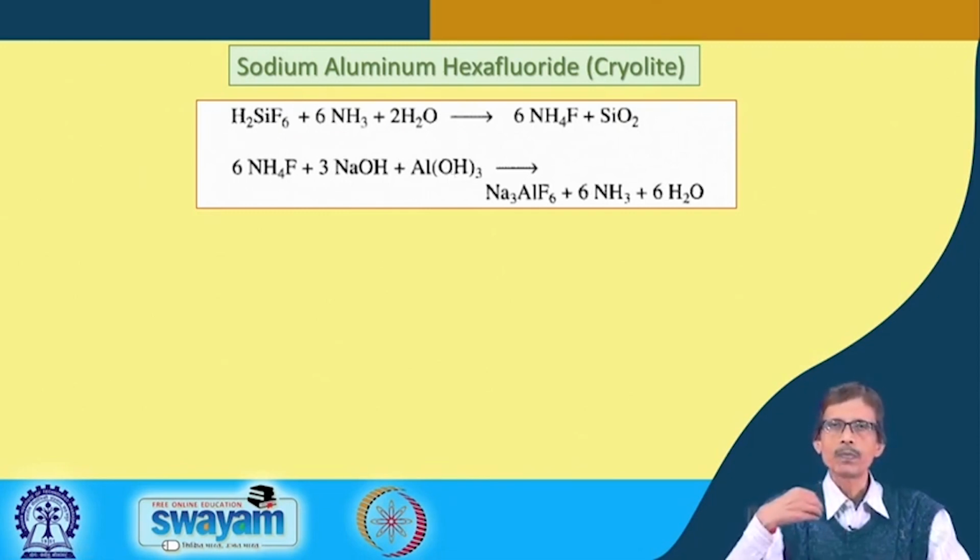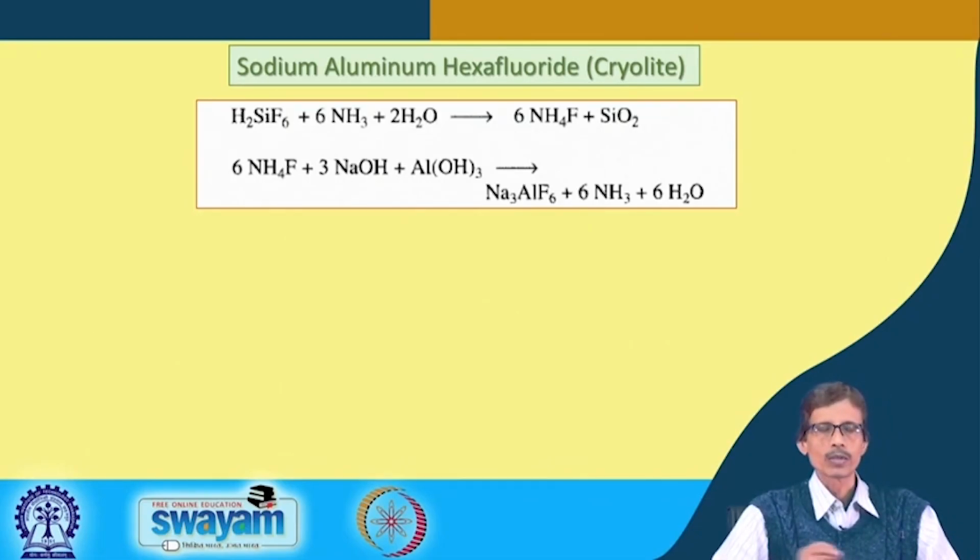Anywhere you can have the corresponding very low grade or very poor quality aluminum sample, you can convert it by alkali treatment in the basic medium. So, alkaline treatment of that particular one gives you simple aluminum hydroxide. Now that aluminum hydroxide will be used for the preparation of cryolite. So, your aluminum hydroxide will be the typical source for making your synthetic cryolite, because that cryolite we can use for aluminum production, the pure quality of aluminum production through electrolysis.